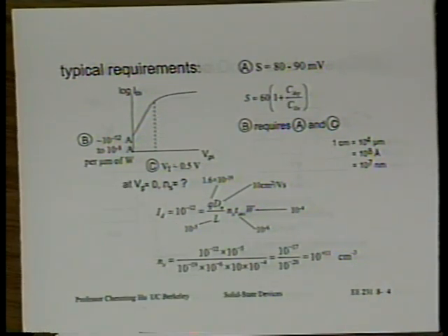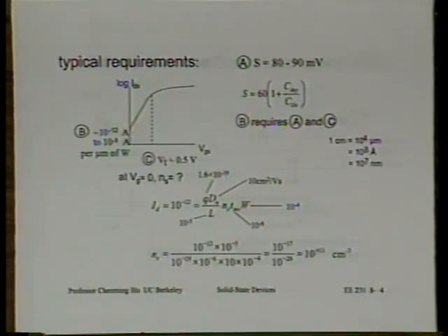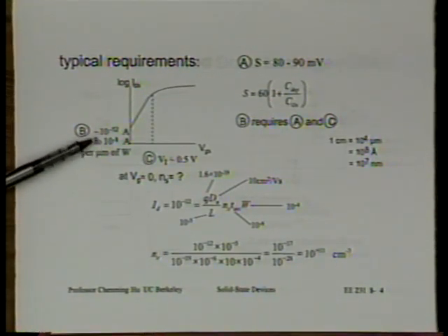And today, 10 nanoampere of leakage per micron width of transistor is not considered large. If you look at the roadmap, a few generations down, we're probably going to tolerate 100 nanoamp per micron, or 0.1 microamp per micron. But today, I would say these two are good numbers to remember.